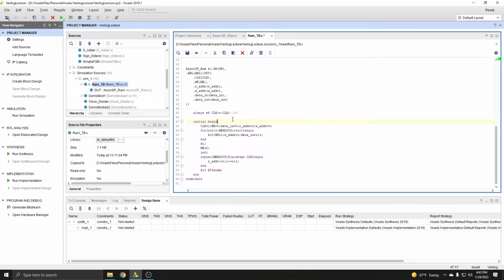In this case, we declare the initial signal conditions. You loop through filling the memory. Now, this delay 10: keep in mind, like I said, this is happening at that clock edge. So I don't want to lower the write enable yet, because if I lowered it right after this for loop, it would still lower it before loading that last location.